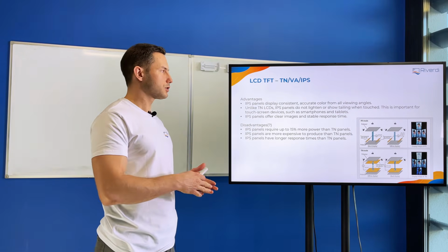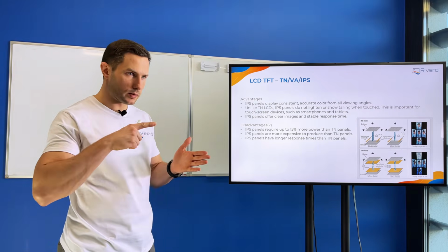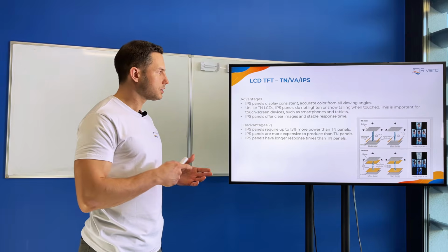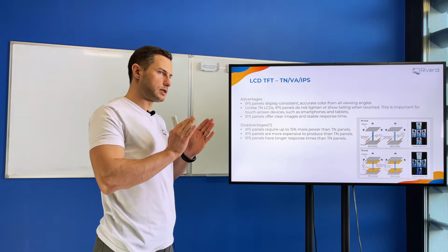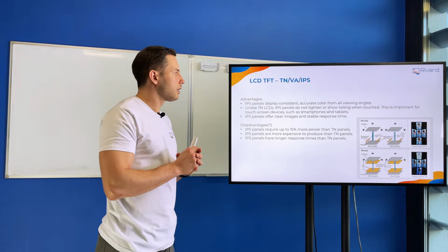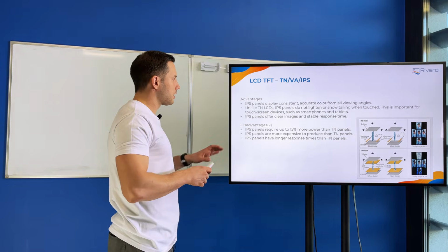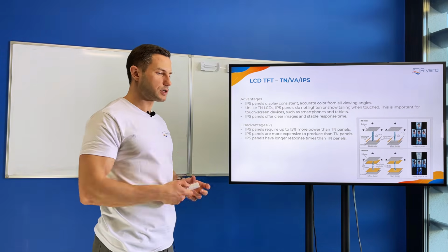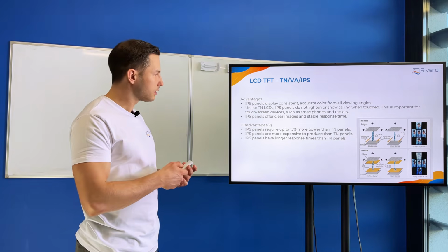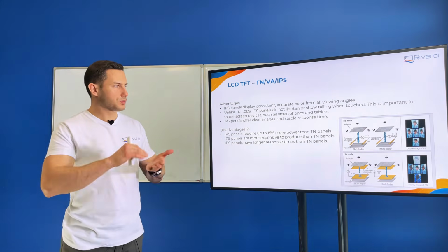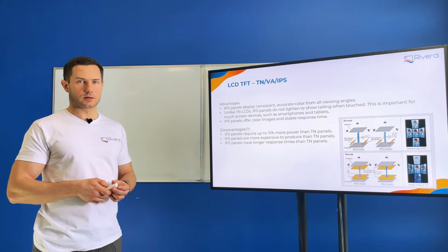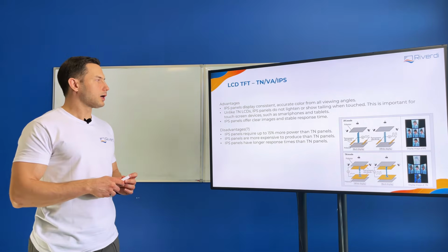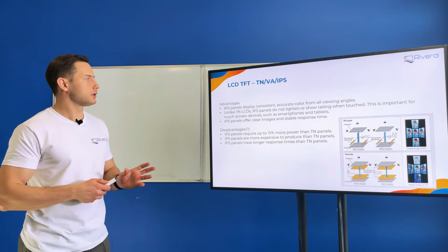When we have a touch screen optically bonded and we touch it, we actually push the display as well, and we squeeze the cells with this mechanical force. When we have a TN display, every squeeze of the cell changes the image suddenly. With the IPS, because we have in-plane switching, a different crystal organization, this effect is lower. It's not completely removed, but it's way lower.